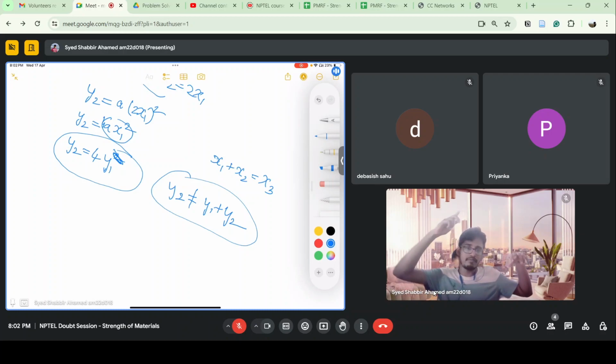So if I apply the load which I was applying earlier, my beam will not bend like this, right? It is very huge. So you can say that due to the applied load, that beam is remaining in the linear region only. But the compromise I have to make so that this remains linear is I am using a lot of material, which increases the weight, which increases the cost of making the beam. Everything increases. So I cannot make that compromise every time.